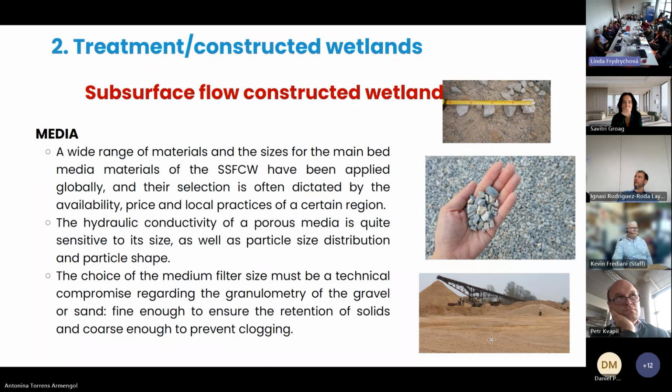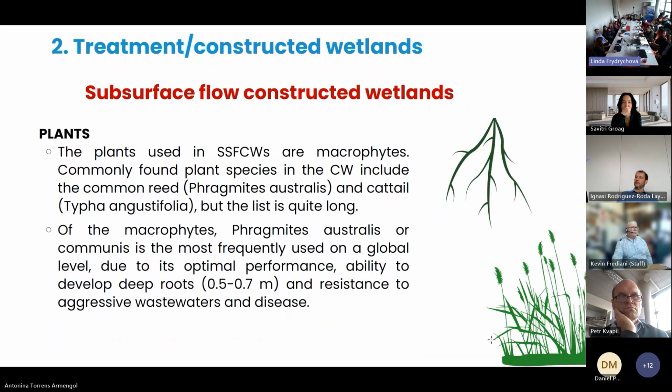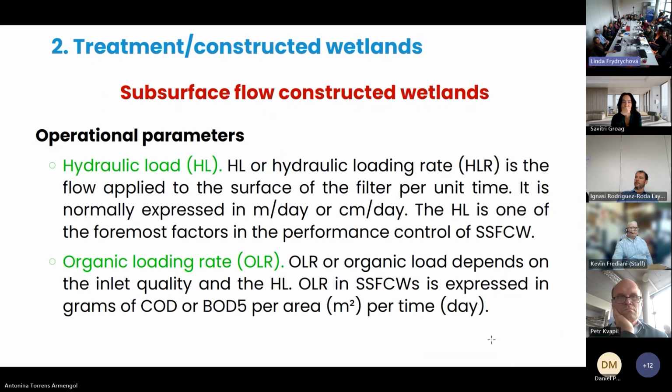This is my key message. The plants are important, but not as much as the gravel or the media. And the two most important parameters are the hydraulic load and the organic load. This is the conventional design approach until now. Now we will see that pathogens are very important too, but okay.